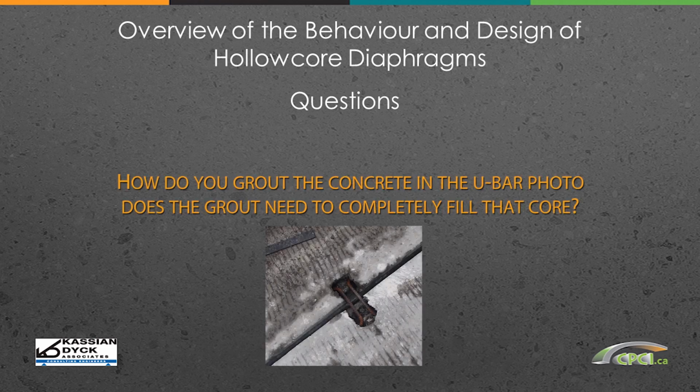Had a question about the connection U-bar detail I showed. How do you grout the concrete in the U-bar photo? Does it completely fill that core? So yeah, that's a detail, again, used in Ontario. I think probably considering shear friction with a bit of a hook on the bar, and concrete or grouting it in, whatever the engineer is doing there, he's probably analyzing it as a tension connection with a bit of hook development length, and would have to fill in that portion of the core and look at what the capacity is